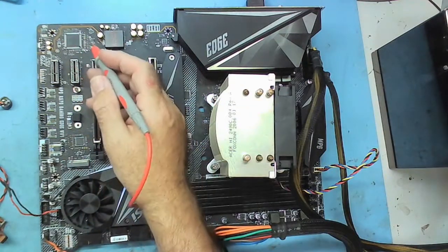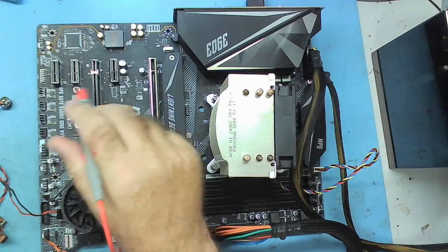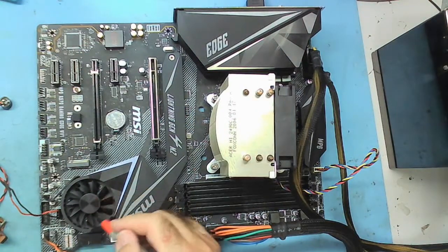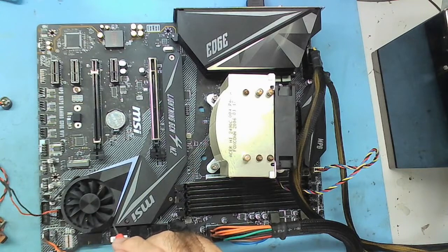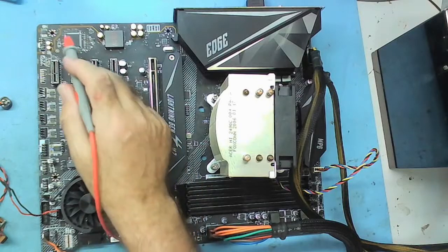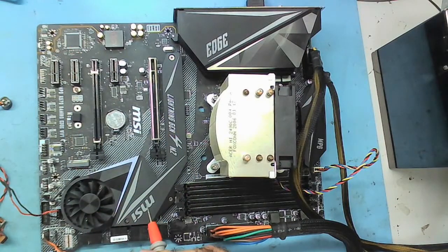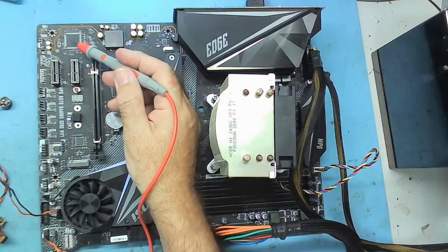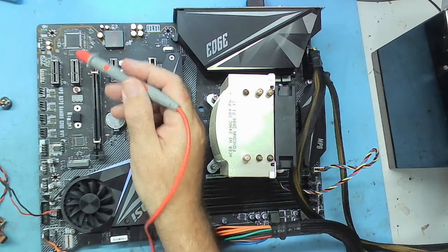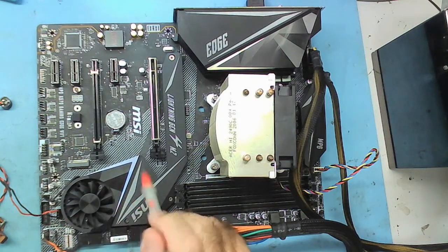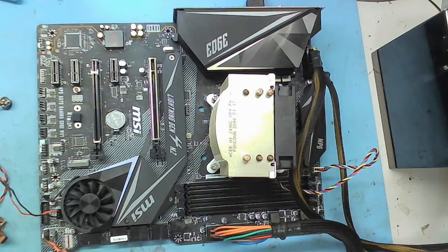When it's all powered up, all the voltage rails are up. This will basically signal to the North Bridge and South Bridge as well, usually. So generally all three are involved before you can power a board up. The Super I/O is involved, the North Bridge is involved, and the South Bridge is involved, yeah. Because they're all involved in powering the board up, there must be standby voltage on the Super I/O, there must be standby voltage on the North Bridge, and there must be standby voltage on the South Bridge, because otherwise it can't start.